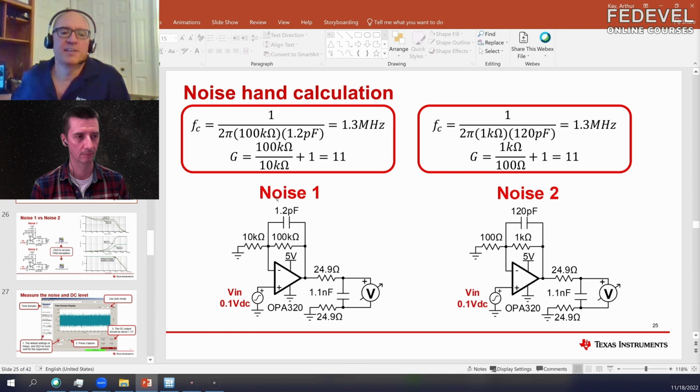And the idea is that you can calculate the cutoff frequency by taking 1 over 2 pi times the R and C. So because the resistor is larger here, we compensated for that by making the capacitor larger over here to keep the bandwidth the same. So the only variable in these two circuits is the magnitude of the resistors. Everything else is the same. And you have this circuit on your development board, and you just switch between them by jumper or something.